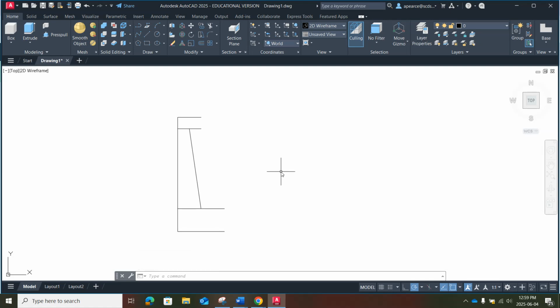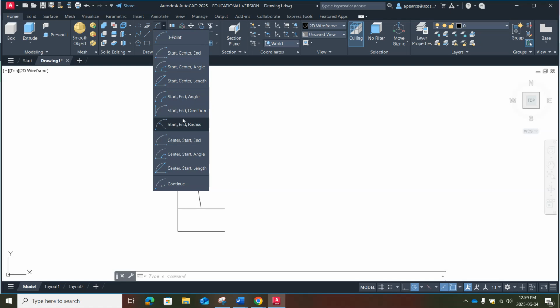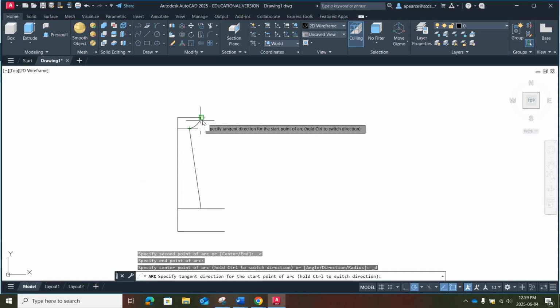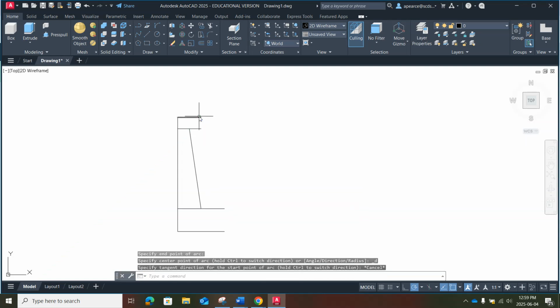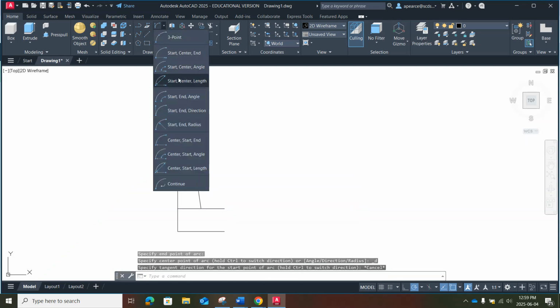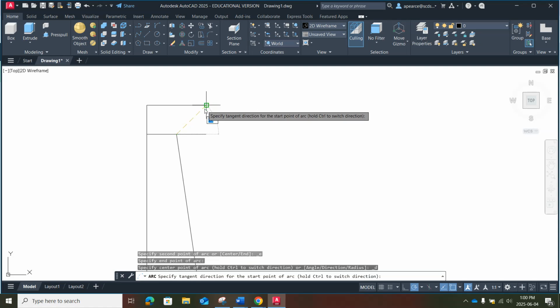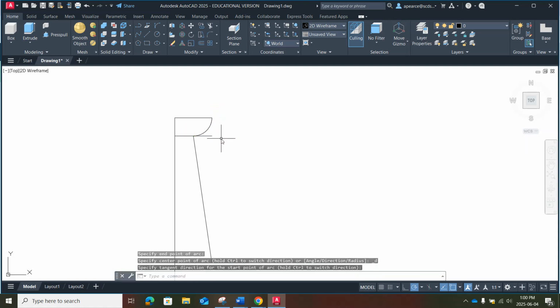So then we've got to go to arc. Start and direction. I'm going to start it here. I'm going to click it here in my direction. Oops, hold on. Let's try that again. Start and direction. I'm going to start it here, end it here, and I'm going to direct it out that way. So it gives us a nice smooth curve.